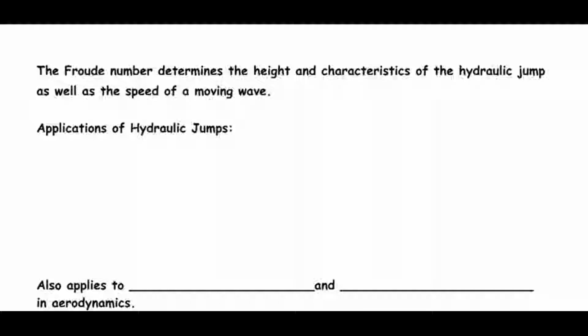So we're talking about waves, both standing waves and moving waves. Standing waves are the hydraulic jumps we were talking about. And all these waves are characterized by the dimensionless Froude number. Also, we can talk about some applications of hydraulic jumps. These aren't just naturally occurring things, but they can actually be used.